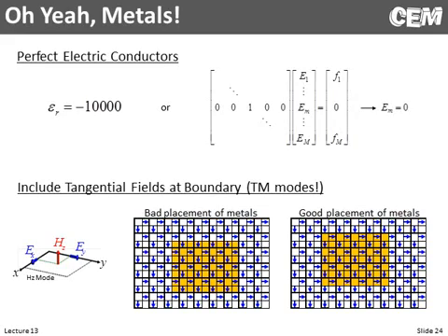Now when I incorporate metals, I tend not to use the 2x grid technique, and I build the device separately on all of the different material arrays because I think it gives me a little bit more control, whereas the 2x grid technique is a little bit abstract when you don't necessarily care about doing this. And for low to moderate index contrast devices, the 2x grid technique works really well. So that's a short story with metals.